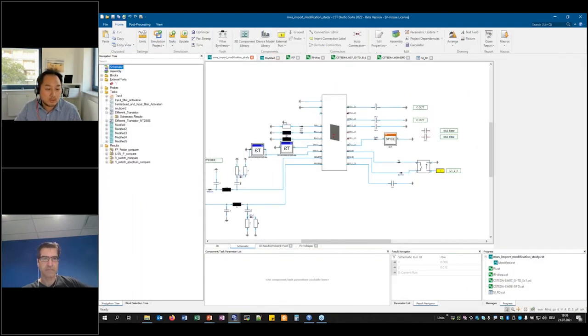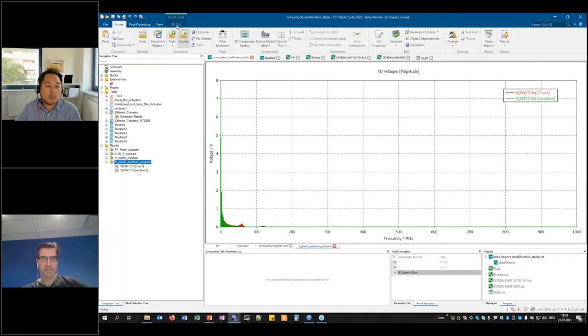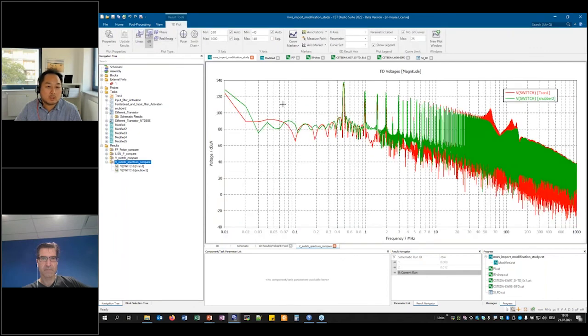So these are the results folders, where you can put as many results folders as you want. You can just copy paste. You can switch to dB microvolt per meter. You can afterwards plot the frequency, with the scaling in log, and then you can see what the impact is directly, if this is my original structure, for example, and this is the one where I define, for example, a snubber at the diode, what kind of improvement I can see. For example, in this case, I have seen some improvement.